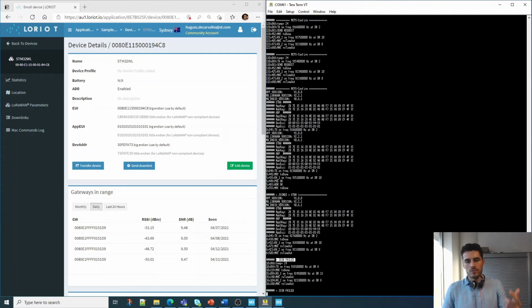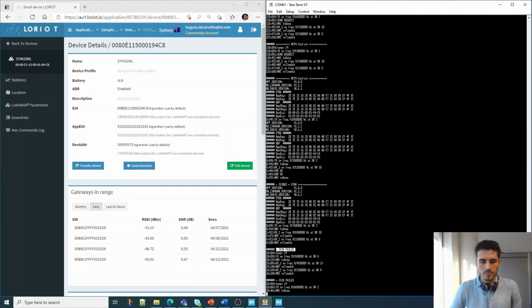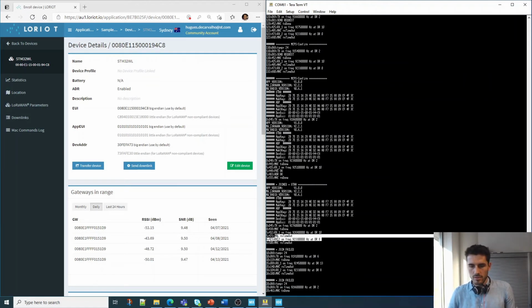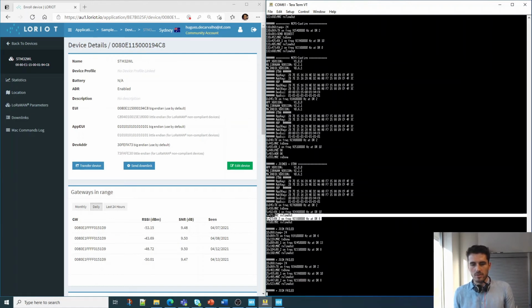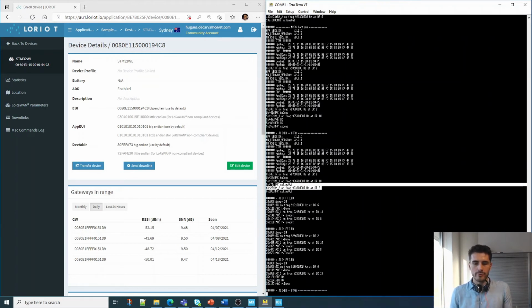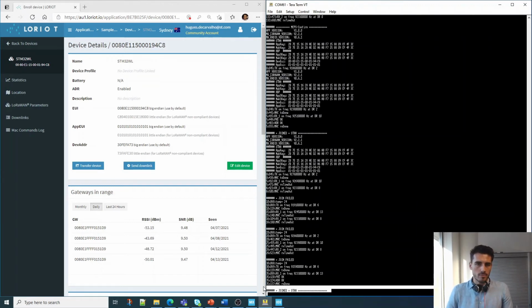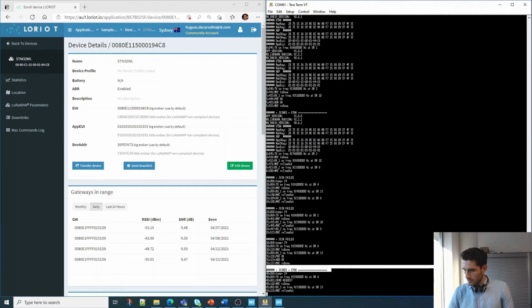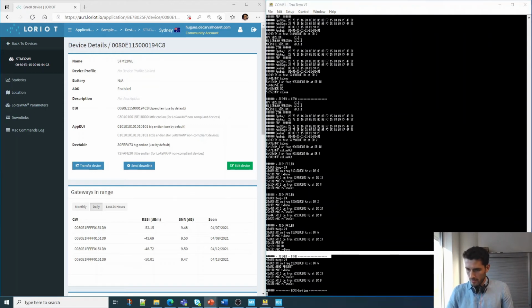You have a join request every 10 seconds, and here it must be trying on some frequencies that are not channels 0 to 7. So it's just gonna keep on failing, and it will eventually work. Yeah, it started working, but sometimes it can take multiple minutes. We don't want that.